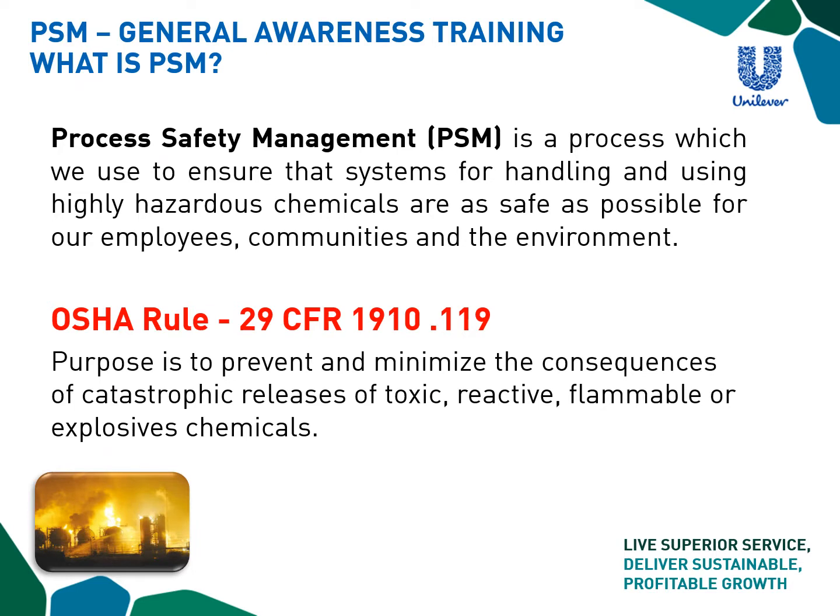So process safety management is essentially a process which we use to ensure that systems for handling and using highly hazardous chemicals are as safe as possible, not only for our employees, but also for the communities around us and the environment. The PSM standard is outlined in OSHA Rule 29 CFR 1910.119. And the whole purpose of this is to prevent and minimize the consequences of catastrophic releases of toxic, reactive, flammable, or explosive chemicals.